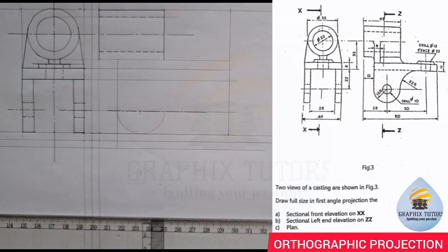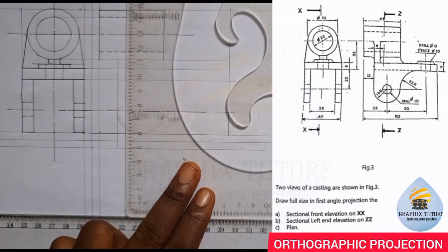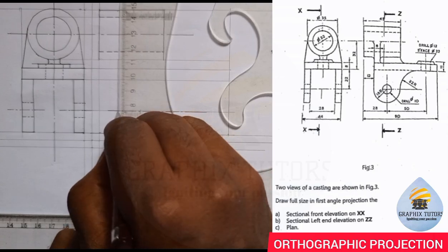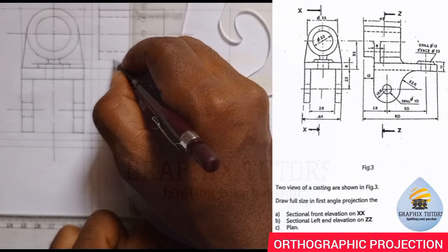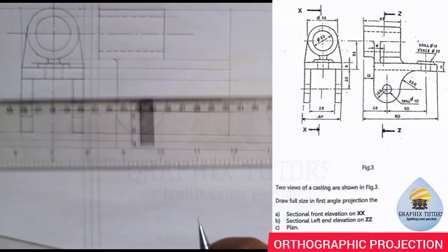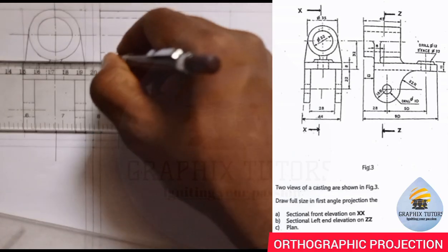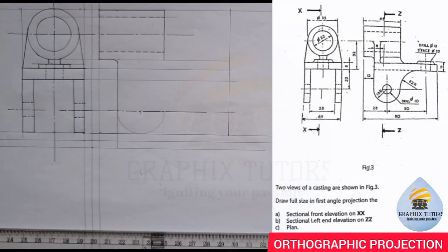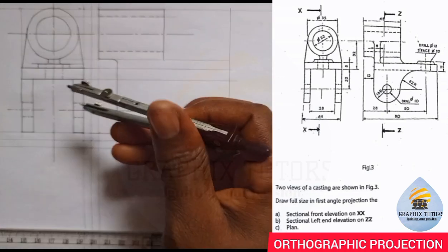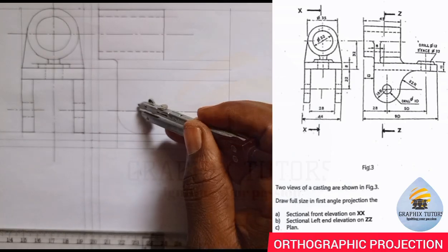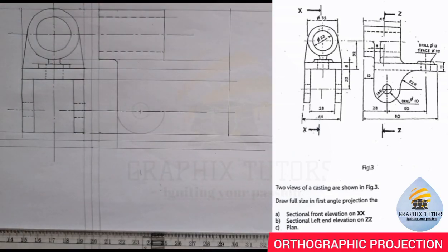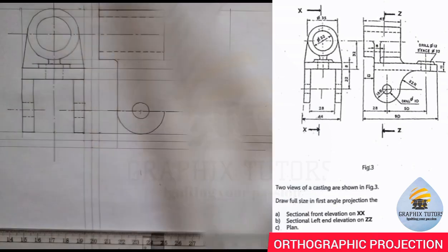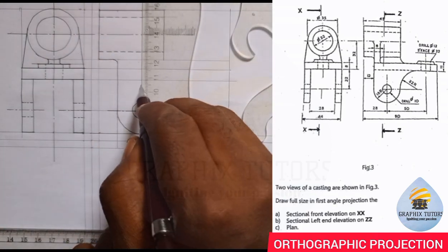So that is where I will now take in from this point here to this point. I can easily just draw a fillet at any given radius here, and I'll just close it up to this point. You can see that. And the internal one is given to be 10, so 5. Five is very small, so I'll just take this is 5 here. So just place at the center here, and I'll do this. Right? So I should be able to trick that out. And you draw the center line here, complete it. Long, short.